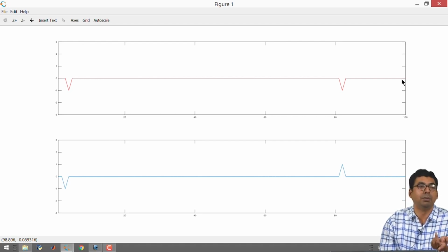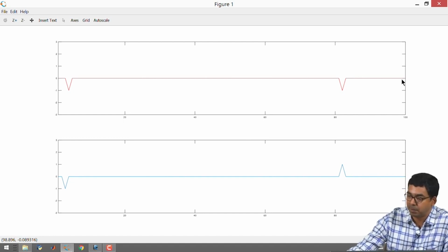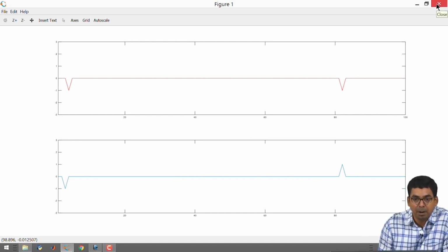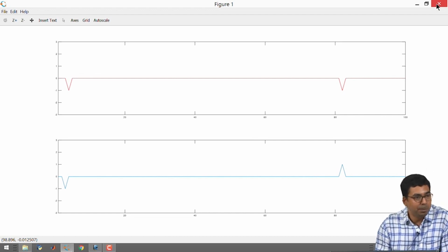It tells you typically what kind of fault has occurred and at which location. So this is known as time domain reflectometry. There is a lot of research that happens with time domain reflectometry. Here we are considering the very ideal cases. In reality, there will be losses in the transmission line. There will be other parameters that you will have to consider, for example, dispersion of the line and all that. But in the simplest form, this is it.